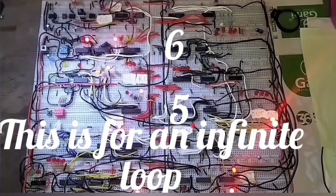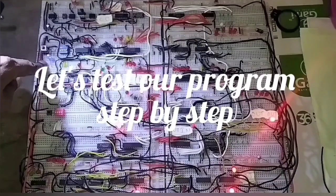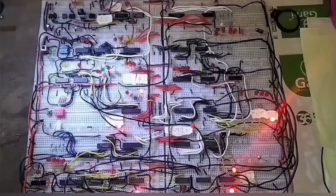We are doing this for an infinite loop. The task of the jump instruction is feeding the value 5, that is the data 5, into the program counter again and again. So we are creating the infinite loop. As soon as we finish the program, we will jump into the infinite loop.